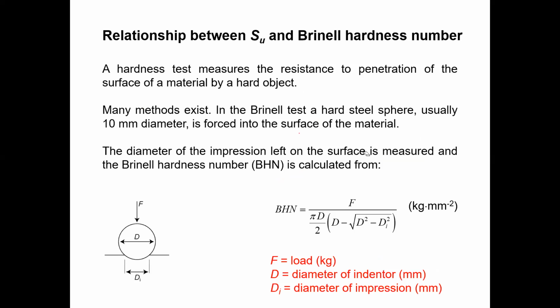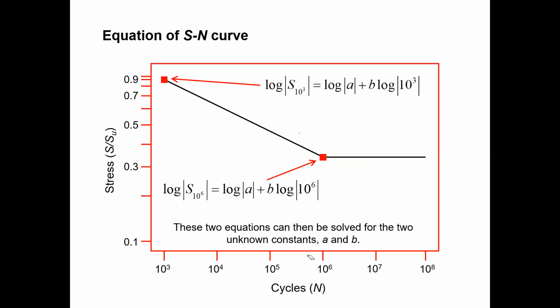Sir, I have a question. Yeah, you can ask. Can you go to the previous slide? Yeah. In the slide, the S-N values are at 10 to the 6, right? So after 10 to the 6 cycles, it won't fail, right? Yeah, it won't fail, but that's at approximately 0.33 stress. So what if we increase the stress? Will it then fail? So no.